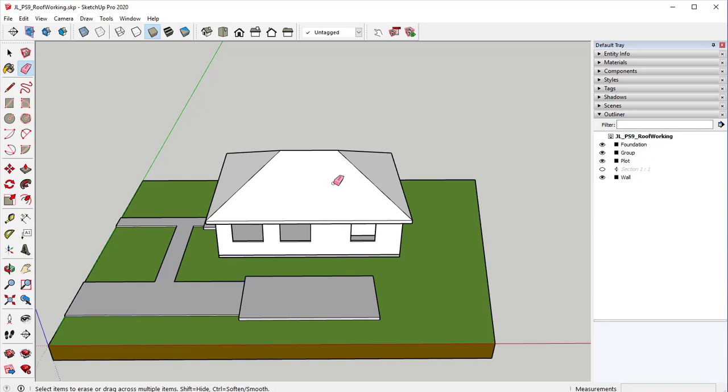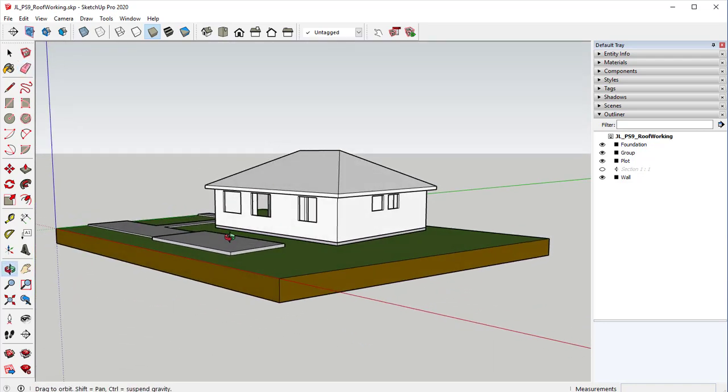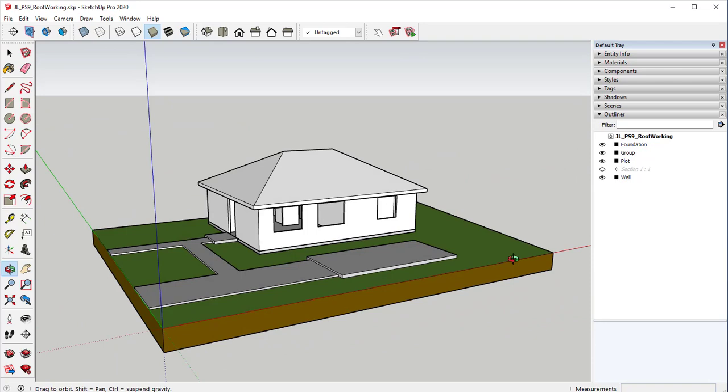There are numerous ways to go about creating a roof inside SketchUp. In order to create our finished version, we're going to use a very simple way to create a hip roof. But because there are 2 different pitches, we do need to modify it at the end. I did want to show you what it's going to look like for our hip roof.